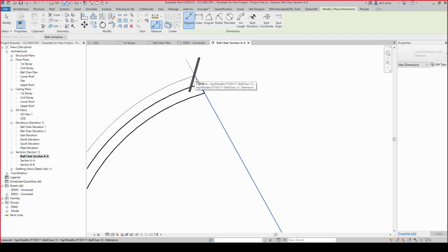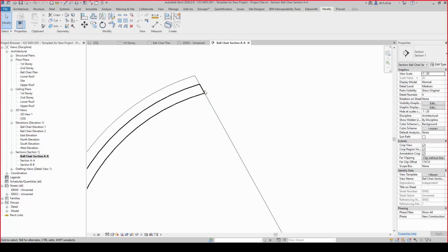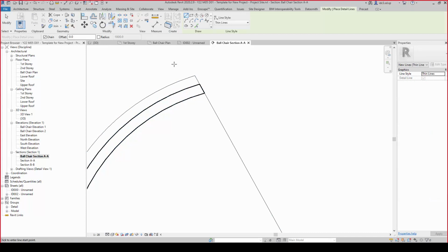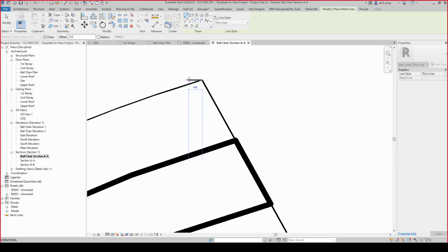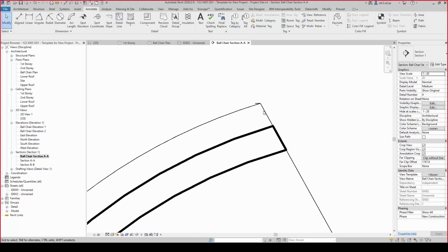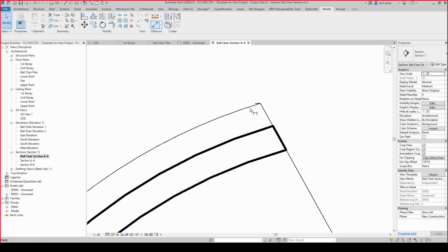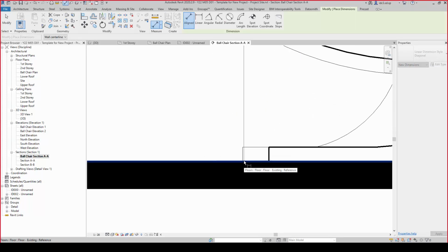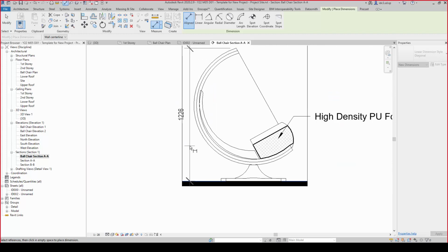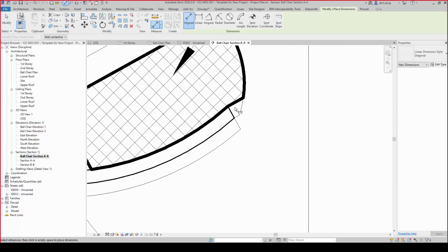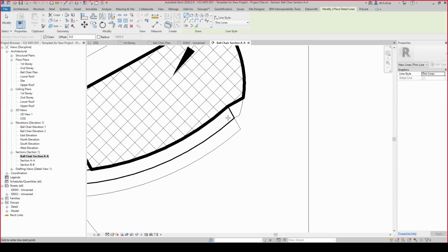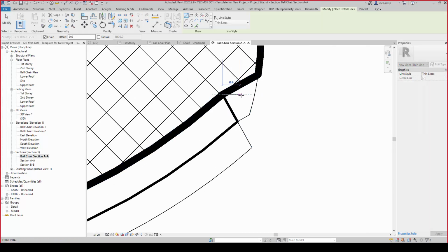So I'm going to section this one. I can't quite snap properly on this, so again I'm going to need help by drawing the detail lines here. So I'm going to just draw a thin small little line like that, okay, so that I am able to snap my dimension tool this way from the top to the floor, so that I can indicate the overall height of this particular object, and probably indicate down here also what will be the seating height, let's say somewhere down here.